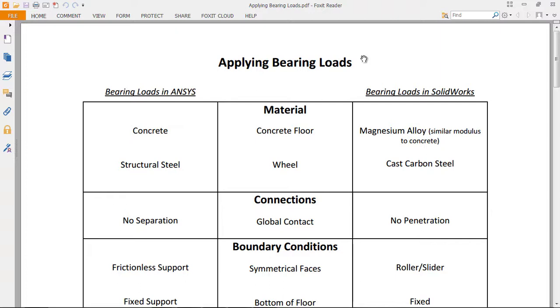In their case, they drew the grips, and then they put the loadings on the grips and let the grips apply the load to the handcuffs like what happened in the tensile test machine. And so with a bolt head, you would create a wrench, or at least part of a wrench, and you'd apply the load to the wrench, and the wrench would apply the appropriate loading to the bolt head. So try to think of it from that perspective. It may actually make it easier as you apply loads in simulations that you may run in the future.